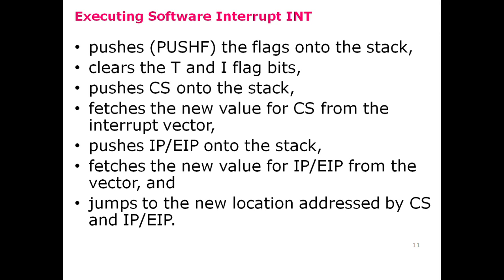Similarly, it pushes the code segment onto the stack because the new content from the interrupt vector would be loaded into the code segment register. So that's why the old content is pushed onto the stack so that the IRET instruction would get it back, so that the controller would return to the application or to the program or instruction where the control has left.